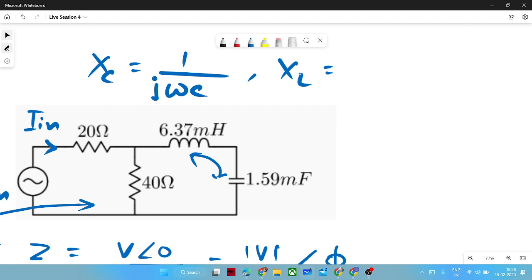Do you have any doubts regarding these imaginary components? Have you studied them? I hope everyone is familiar with basic circuit analysis. So XL would be j omega L, and resistance is generally written as R, with no imaginary component. So now you just need to add XL plus XC in parallel with this resistance, and the whole is in series with this resistance, and that expression will lead you to some magnitude and some angle, and that angle will be your power factor angle, right?